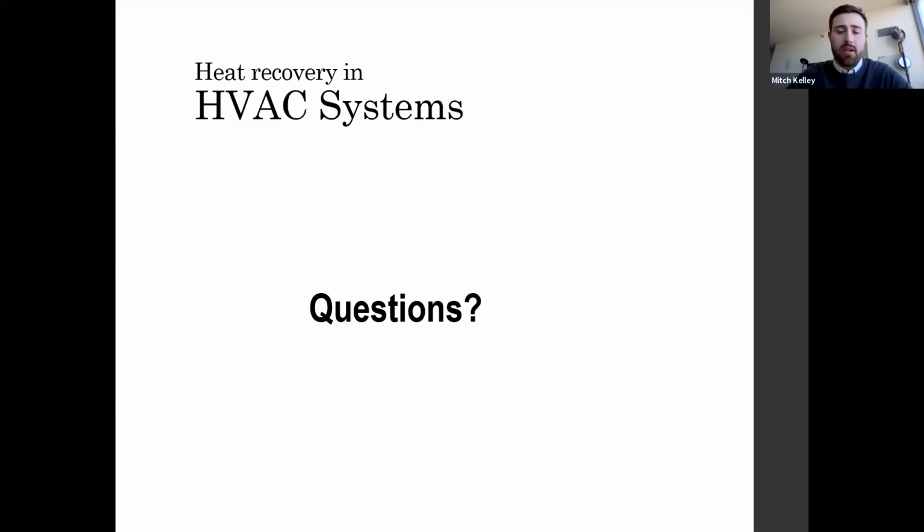Basically, what you do is you take 2 water coils and you strap them on the side of an air-cooled chiller, and you take advantage of the condenser fans that already exist on that machine to run cold ambient air over those water coils. You send the water that you're using throughout your facility for your air handler cooling coils, or maybe it's separated by a loop and a plate and frame heat exchanger, out there to get cooled down by the ambient air temperature as opposed to having to use mechanical cooling. Great application and something that I think people should start taking advantage of more.